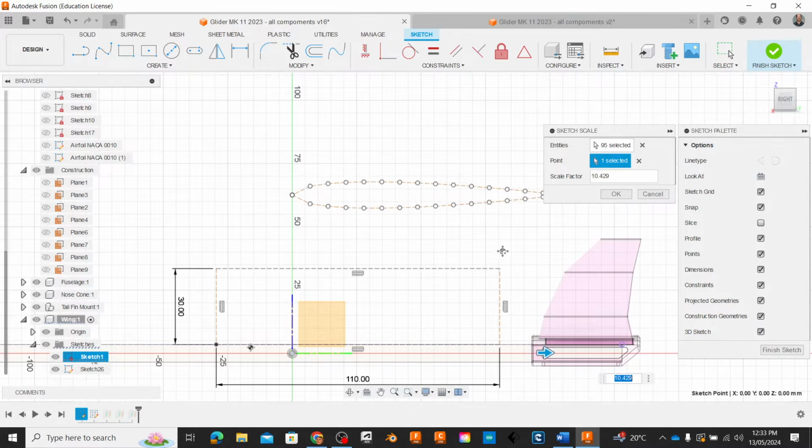And I can check the diameter of this circle here, radius diameter, just under 1 millimeter. That should be okay. If you're not sure whether some of the lines are actually tangential, so this is a tangent symbol here, that little circle with the line on it. What you would do is select this line, and then select tangent. Okay? So that will reorganize that line to ensure that it's tangential. That'll be under constraints, okay?